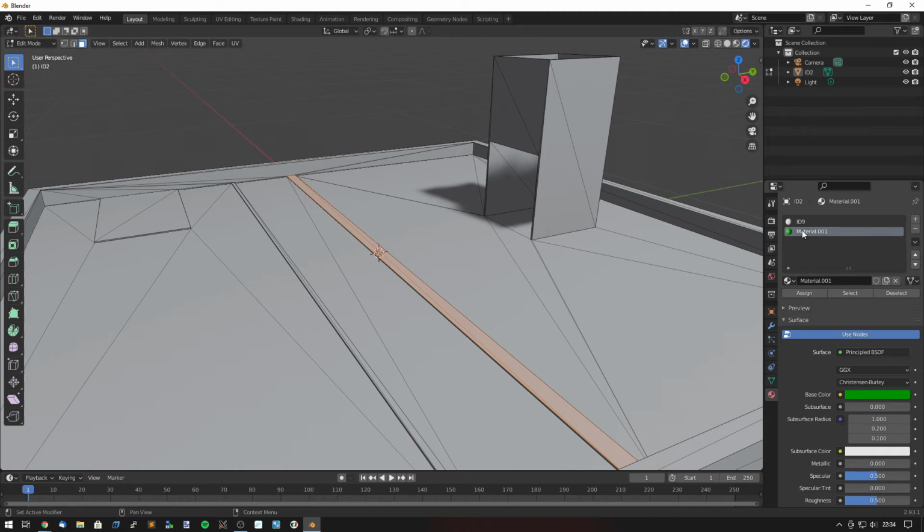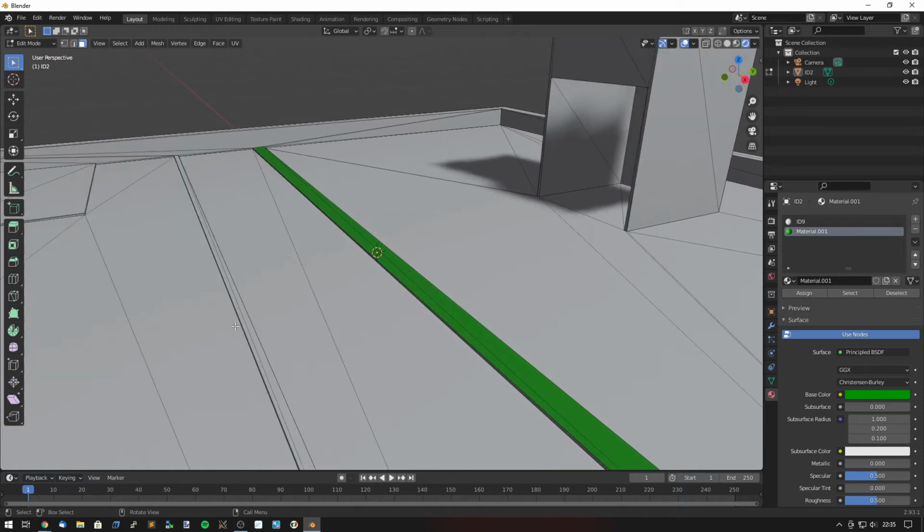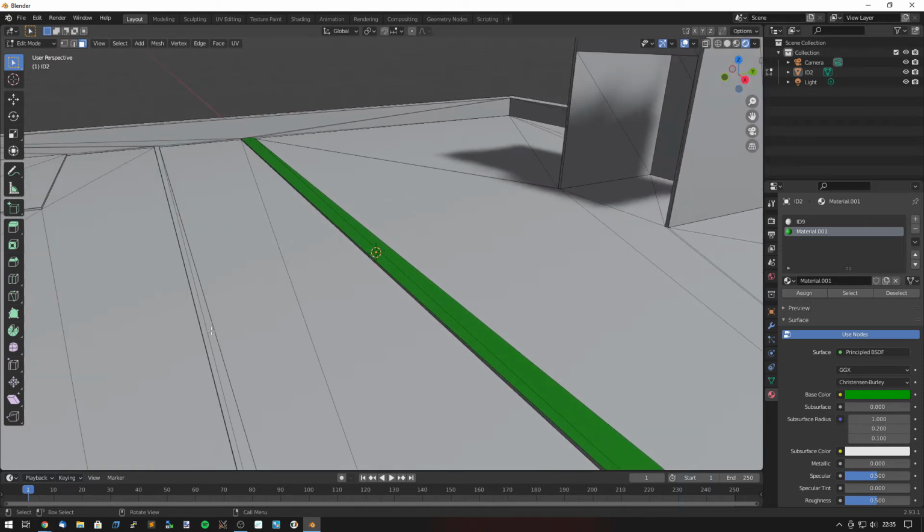That's created a material, but it has not changed the color of the model yet. Make sure you've still got the object you want to be colored selected, and then just hit assign, and it'll assign that particular part that color. Then I can click off and it'll have taken it. Same for the other line here. I want to click and drag on those two triangles there.